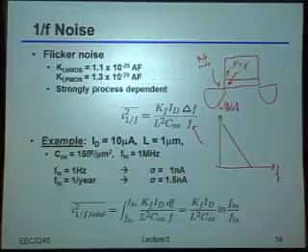And obviously, statistically speaking, the more electrons that could possibly get stuck, the larger the net variance of the final noise will be. Now, this is not to say that electrons can't jump back out or holes can't jump in or whatever. They actually could. But the point is that the longer you wait, the more of these independent events you add up. And so the larger the final variance of the noise you see will be.